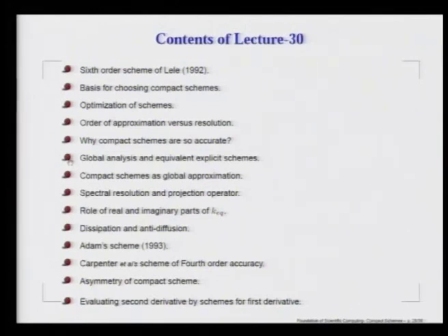So, this is one of the plus points of compact schemes as a global approximation, and we have further developed the spectral analysis tool by finding out the resolution at any node for a non-periodic problem in terms of a projection operator. That is what we are going to talk about.